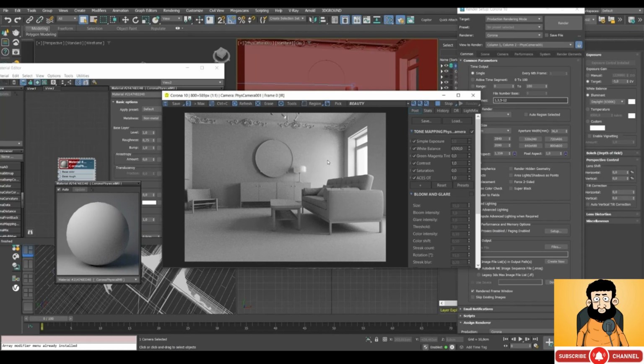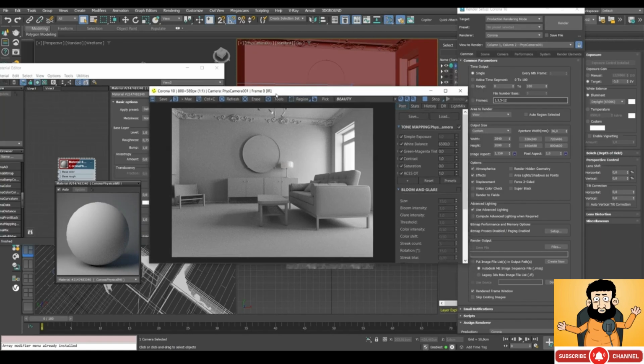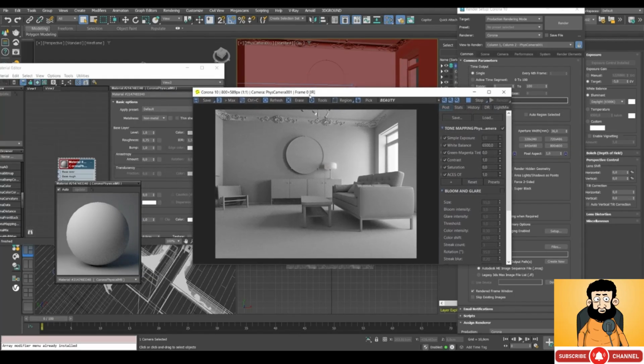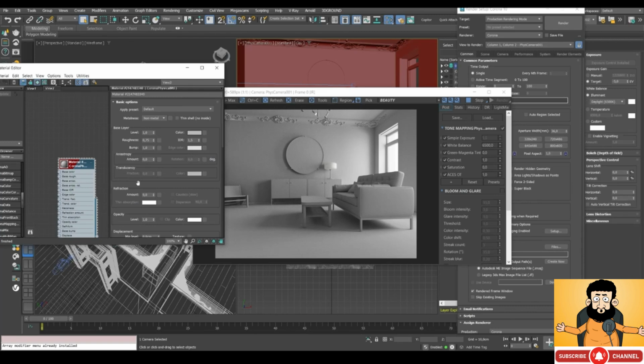All objects in our scene have a clay material assigned to them, and we can proceed to setting up proper lighting. So if you have a darker render with dark walls, dark ceiling, and floor, and so on. Now, I'm not talking about situations when you have just one dark wall, or when the walls are dark while the rest of the interior is light. It's not considered a dark interior. If most of the materials you're using are really dark, you can correct the color of clay material in order to set up correct lighting.